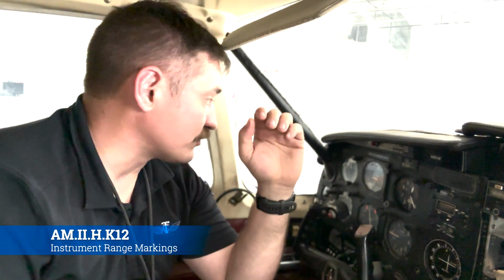Now there's a red line at right about 250 knots, and that means that's the VNE. V speeds will always be V equals speed, just like in physics, and NE is never exceed. Don't go faster than this, because the plane's not rated to fly that fast. So if you get into a dive and you nose over, there's nothing saying that the wings won't come off, because there's so much pressure on them due to that indicated airspeed. The plane will literally just fly apart.